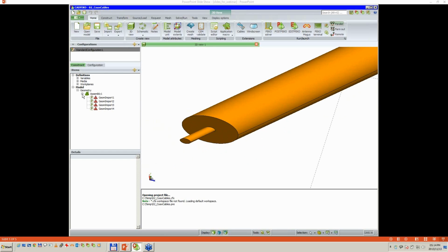If we go to the model tree again, you see some red exclamation marks. Part contains geometry faults. If we go into the detail tree, for example, loops inconsistent. So we have some problems there. Also, face 3, topology's geometry is not G1 continuous. Okay, so let's select simplify part representation.